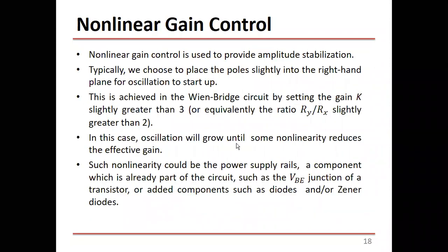Okay, so this is the same thing. How to do this? There are several techniques actually of doing this. The first technique is to leave the power supply rails to limit. You know that any operational amplifier is supplied by VCC and VEE. So leave these supplies to limit to make the clipping levels.